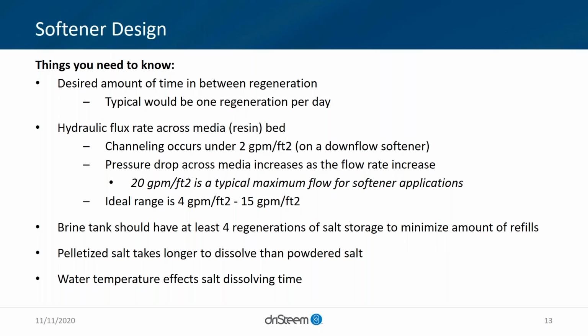So a lot of situations where we're looking at city water pressure, if the plant's not boosting it or the facility's not boosting their city supply, we're looking at 40 to 50 PSI coming in. Well, obviously we don't have a lot to work with if we need to distribute that through the plant. So we want to minimize the essential pressure loss through the system.